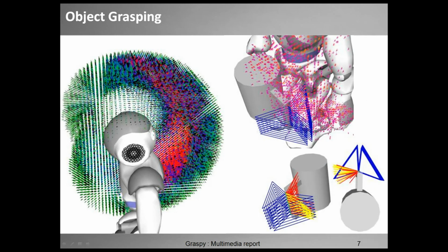The grasping function finds a valid motion path from the current hand pose, and thereby enables me to grasp an object. Since my processor is limited, as well as the degrees of freedom of my arms, I use a reachability map in my motion planner for efficiency. By doing so, the workspace of the hand is pre-calculated and discretized with a cube that is divided into equally sized smaller cubes.